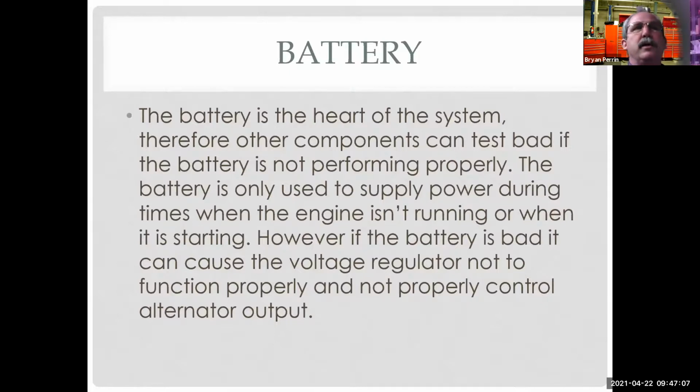Because once my battery voltage gets down below about 9.6 volts, computers start forgetting things. So even though my car may still start, it might wipe the memory on some of the computers. And in European vehicles, that's even more sensitive because some of them have problems under 11 volts. So, very, very voltage sensitive. My car might start, but have other issues.